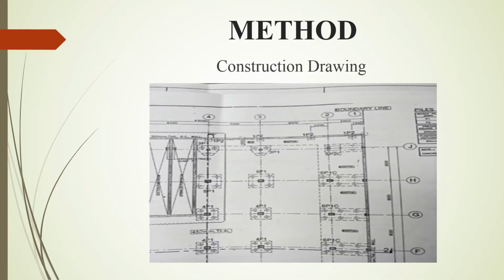Construction drawing. A construction drawing is a plan to show the grid lines of all positions of the bore piles, footings, and columns. A complete set of construction drawings usually contains floor plans, elevations, and sections. All the survey data such as coordinate and reduced level tables will refer to the construction drawing.